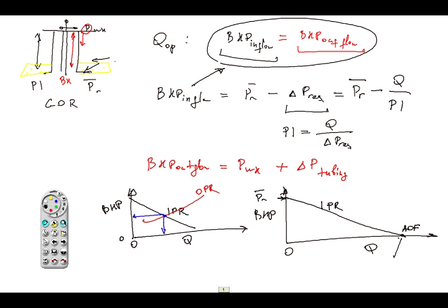So my rate here is equal to PI multiplied by reservoir pressure. Okay, I have these 2 points. I connect them with a line, and now I have my inflow performance relationship. Let's do this for this particular problem in Excel.